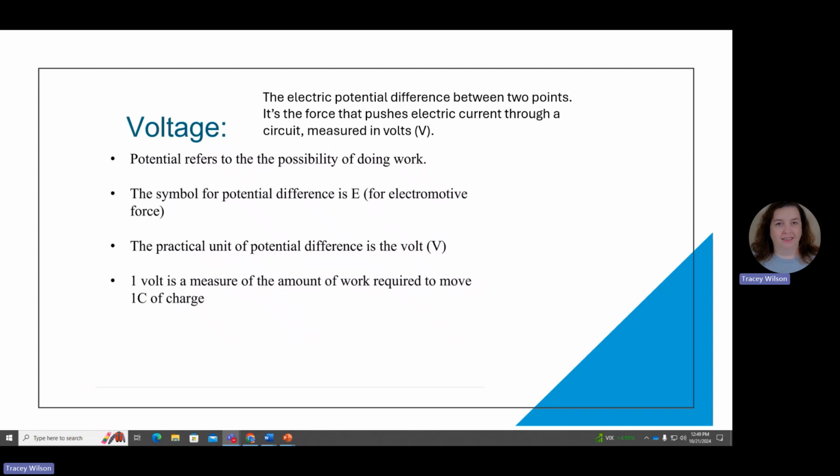So your battery is a 9-volt battery. The Arduino usually needs things to be more like 5 volts. It has a 5-volt input. And then we have resistors and capacitors that will impede or increase that voltage based on what we need it to do. But voltage is very important because some of the components that you have in this kit have a limited voltage they can take. And if you overdo it, you will burn them out. Hence the smoking smell and the electrical burning smell we have had in class.